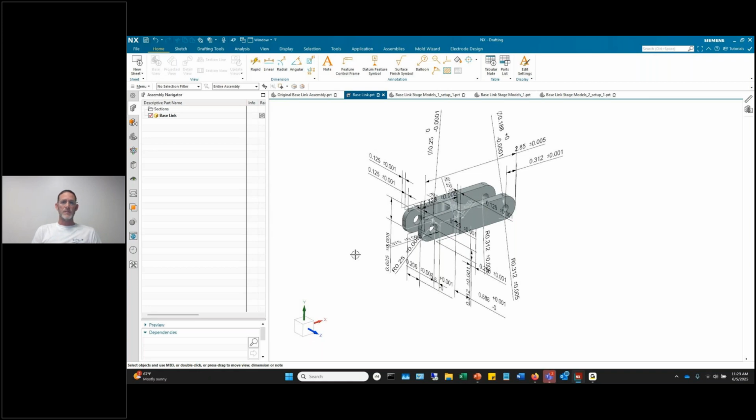ancillary and supporting data. You're going to have to create a plane that's relative to wherever your zero location is. And then in the operation, you're going to have to say tool, plane, operation is going to be done here. The post processor uses the plane to drive the tool's motion. NX doesn't need any of that information.